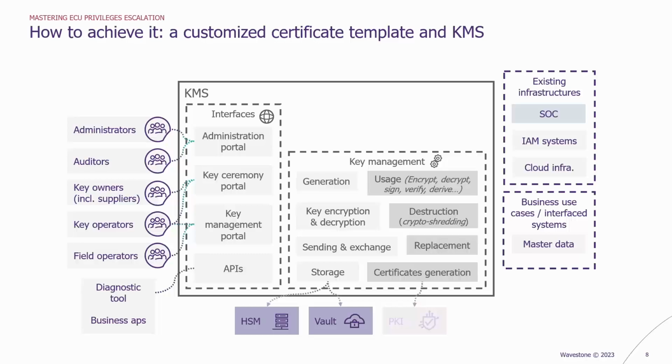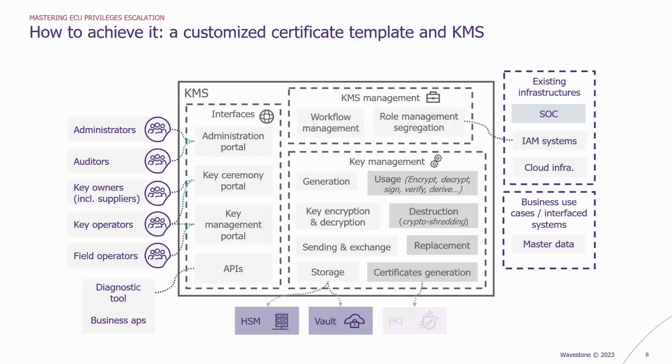Key operators, field operators. Field operators are my car mechanic, basically. And you have some tools discussing directly. Your diagnostic tool most likely is directly discussing with your KMS through APIs, because you don't want any human interaction when your car mechanic wants a key. And of course, at the back of it, you need the management of the tool itself: workflow management, role management, segregation, etc. This is a heavy security tool, as you've guessed, because it's enabling a security feature that is unlocking my car. So you need strong management over it.